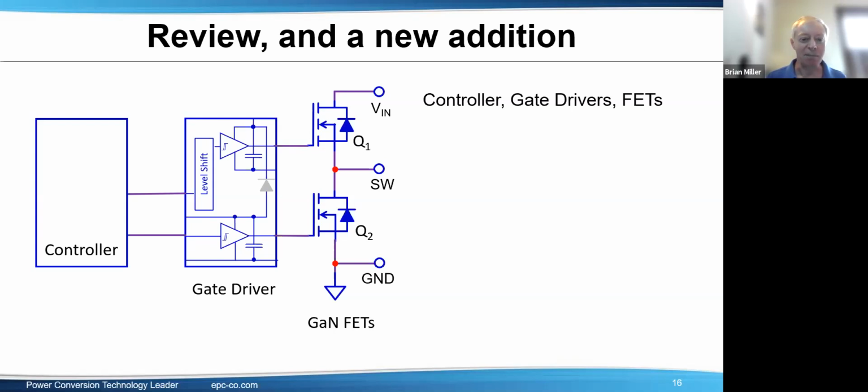There are some designs that add capacitance from gate to source to lower the effect of a transient coming in the drain, so that you would basically change the ratio by adding capacitance. But that typically isn't needed.